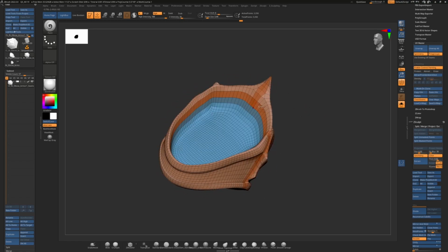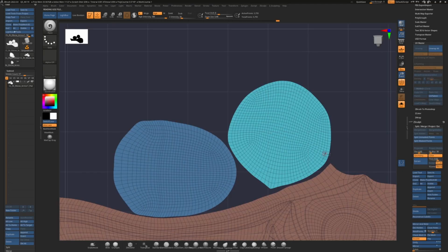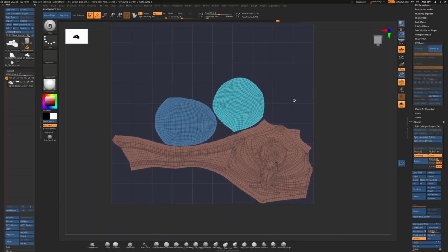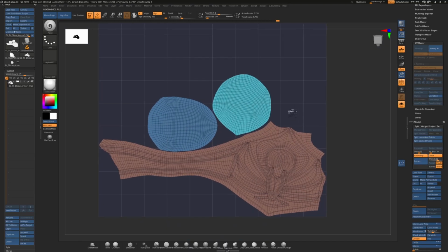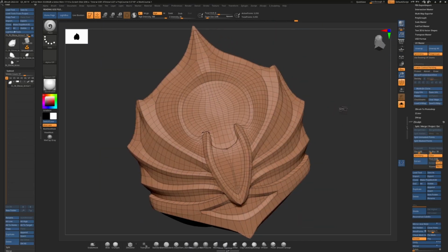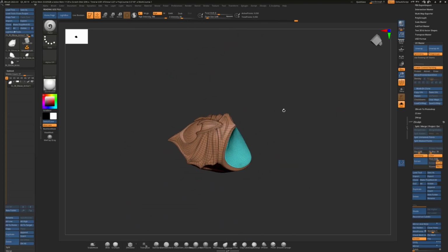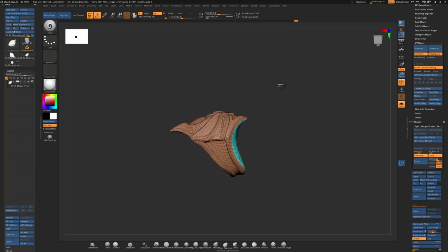Consider we have like an inner edge loop. A lot of times if you have an inner edge loop like this, you're going to have problems with how it separates, especially when you have something like points or cones that have concavity or peaks in them. So once again, I'm going to take a look at the flattened version of this and try to decide if that's exactly what we want to do. I think we'll keep it. Because again, like I said, I'm trying to think about how it's going to be. Your arm's going to be like this. And I think that's an ideal area for a seam.